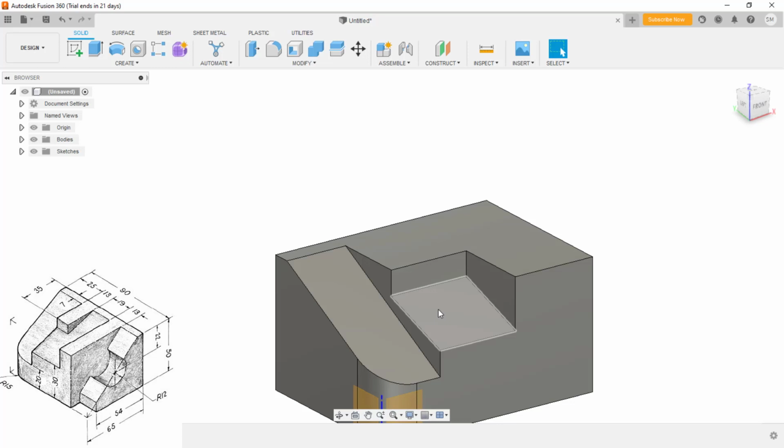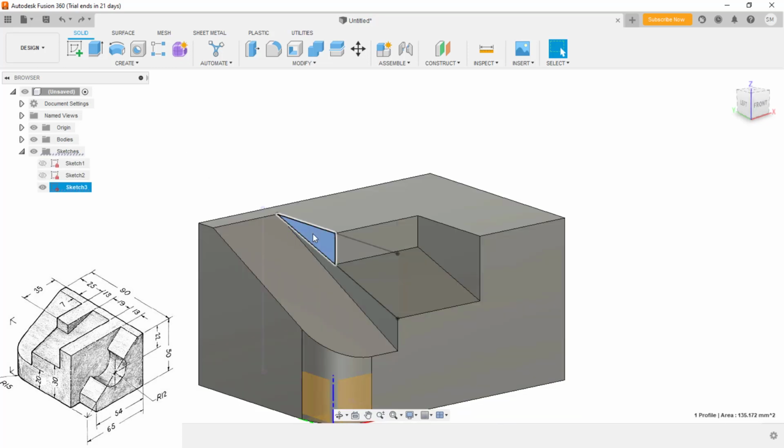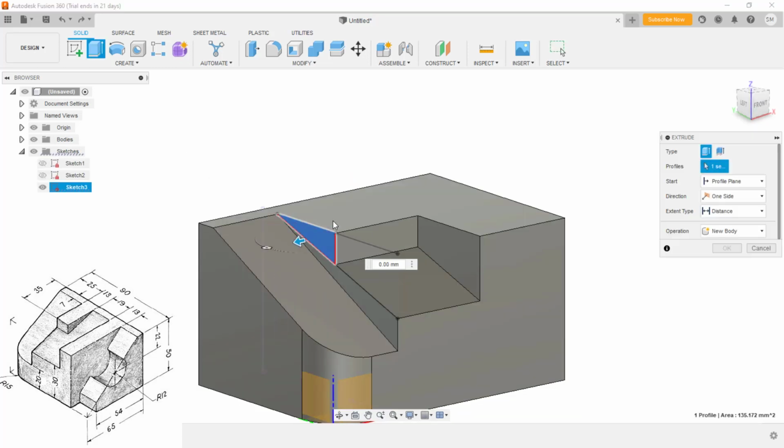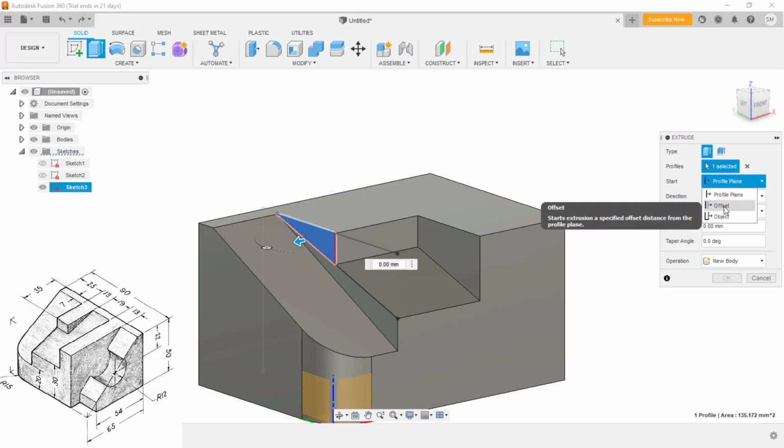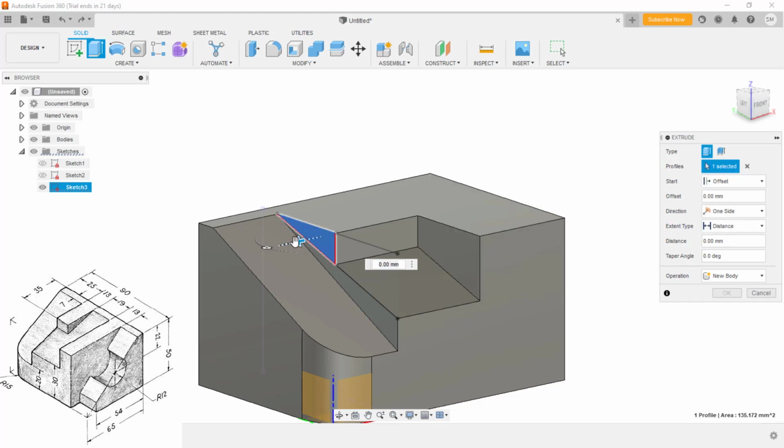Yep. So now again I'll use the same sketch. You can show this and right click on it and use the same method. So this time I'll use the offset. The offset distance is 13. I'll specify it, and you can offset it minus 13 and not minus 20. Here you need to specify 13. It is flipping this side, so minus 13 here you add it.